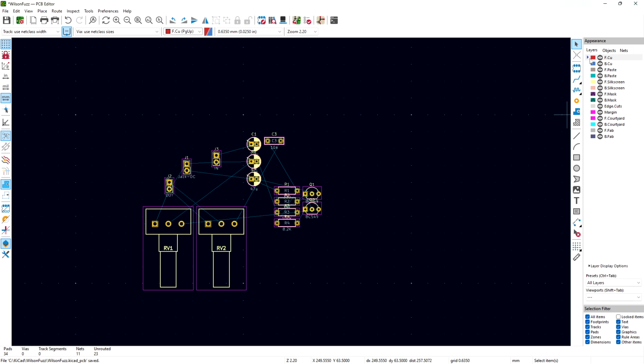So here are our layers. We have the front copper layer, and you can hover here, the back copper layer, solder paste, etc. Silk screen, we're going to come to that. We don't need to worry about most of them, but we'll see what is important. The one that we care about is this edge cuts, which is how our board is going to be cut out, and you can do fancy stuff, but here we only care about 35 by 27.